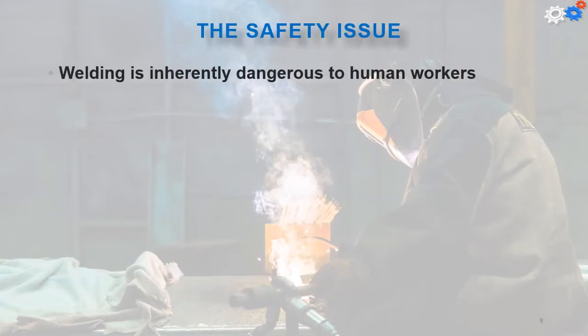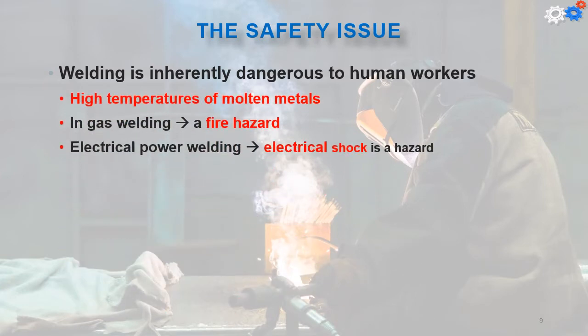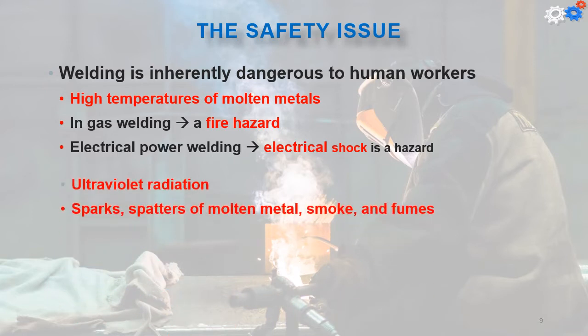Welding is inherently dangerous to human workers. The risk can be the high temperature of the molten metals. In gas welding, we may have a fire hazard. In electrical power welding, the hazard is mainly going to be electrical shock. The ultraviolet radiation, sparks, spatters of the molten metals, smoke and fumes are mainly related to arc welding processes.